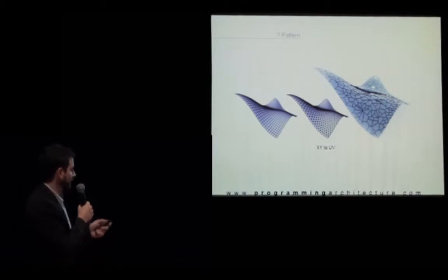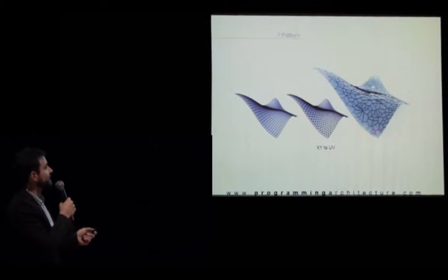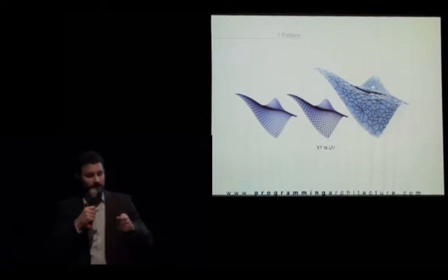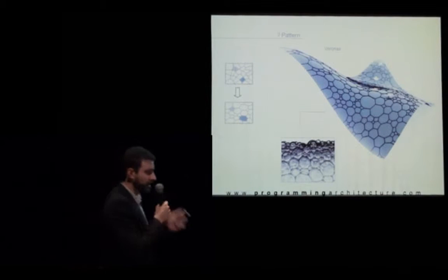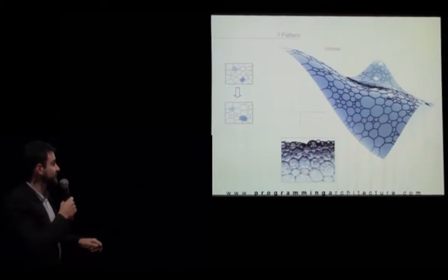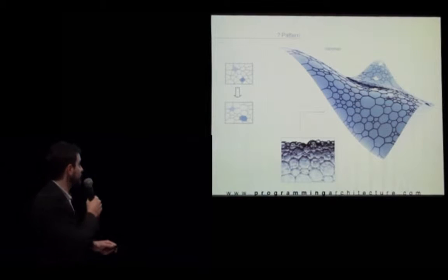But then I thought, this Voronoi diagram is really statically not acceptable. If you look at these cells, they're very irregular. You have some very small members and you have some very big members, and then the angle difference is big. And then I thought, why don't I use this relaxation tool to relax Voronoi over the surface, keeping it on the surface, which I did. And this type of structure I called Voronex in my PhD.